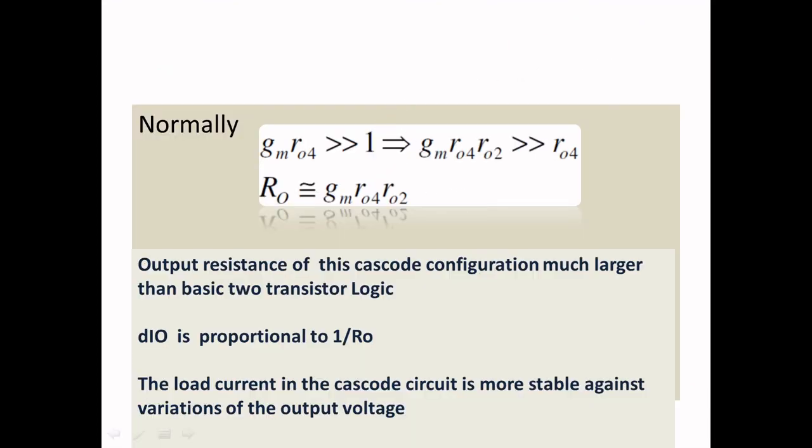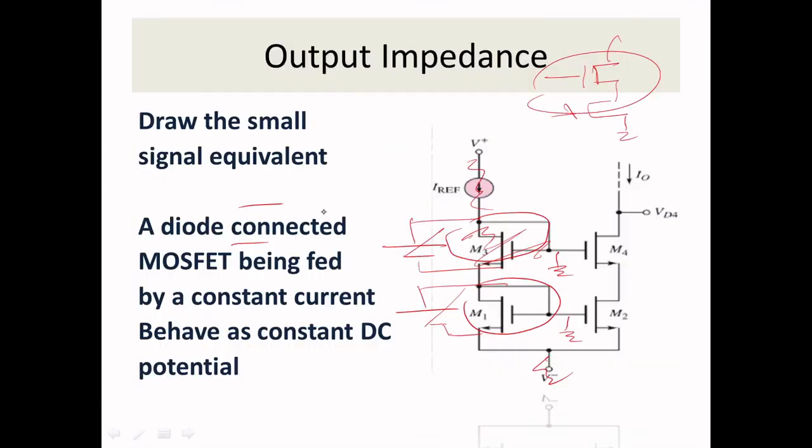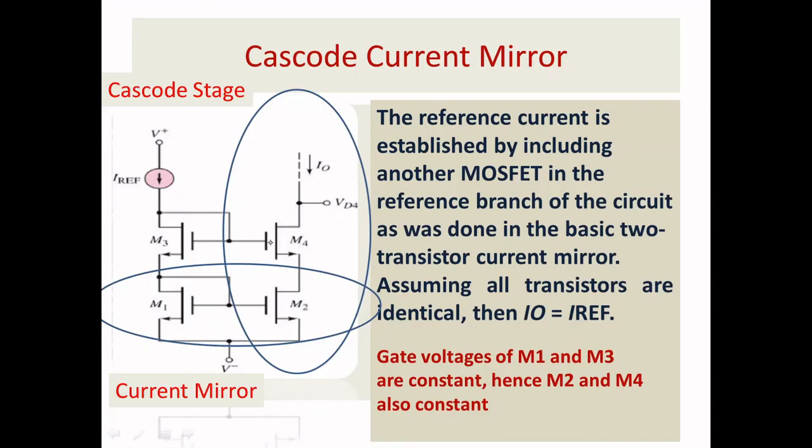So what you finally understand is the resistance was increasing when you go for the cascode, the stability was increasing, and also by choosing the proper bias voltage, the change of VDS2 with respect to I naught also can be minimized. Another thing, this bias voltage was fed through the M3 transistor by finding the bias voltage mathematically. So that is about a cascoded current mirror.